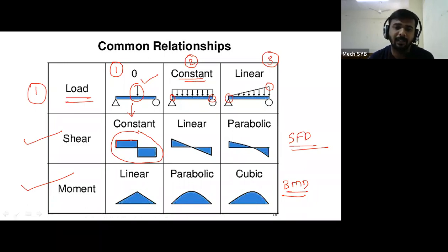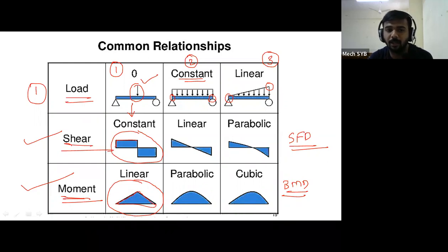And in addition to that, this point load will be represented in the form of an inclined line for the bending moment diagram. If you see the next figure, what does it indicate? The second row is for the shear force and the third row is for the bending moment. Means if your beam is subjected to a point load, its SF calculation will be represented by horizontal and vertical lines, but its BM calculation can be represented by an inclined line.